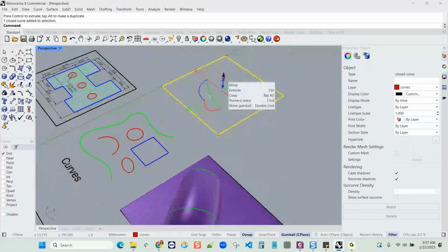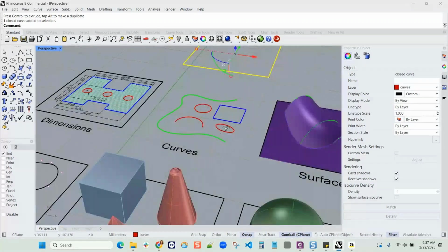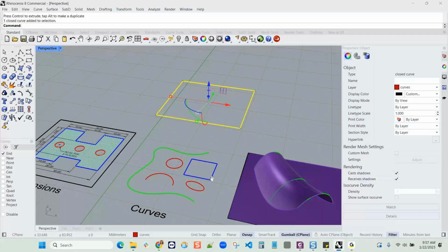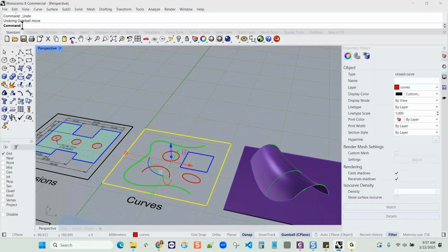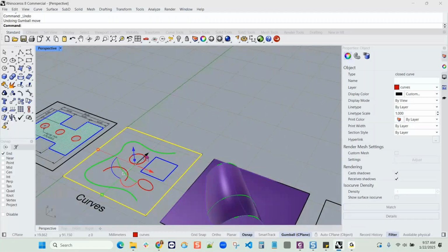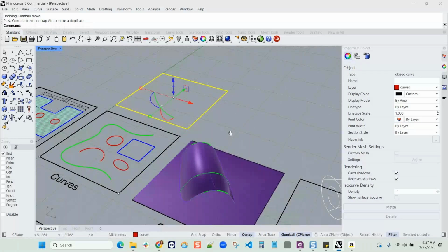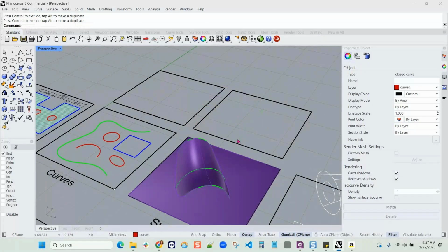So if I pick on the blue arrow and type in 5, it moves it above the construction plane. Okay, so you can move, and let me undo those. You can also copy. So if I drag that and tap the Alt key, I can create a copy. Drag it, tap the Alt key.